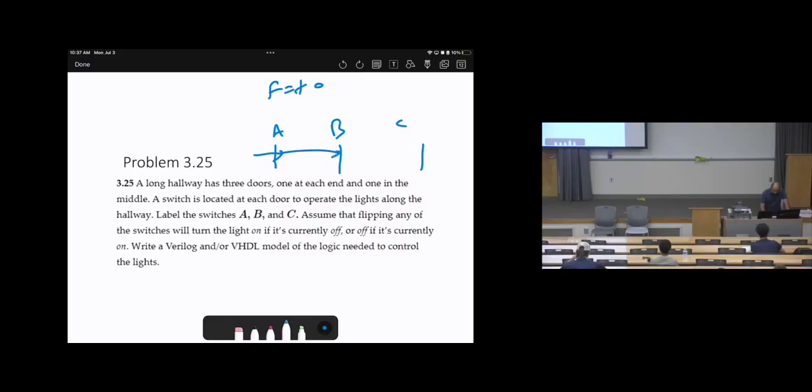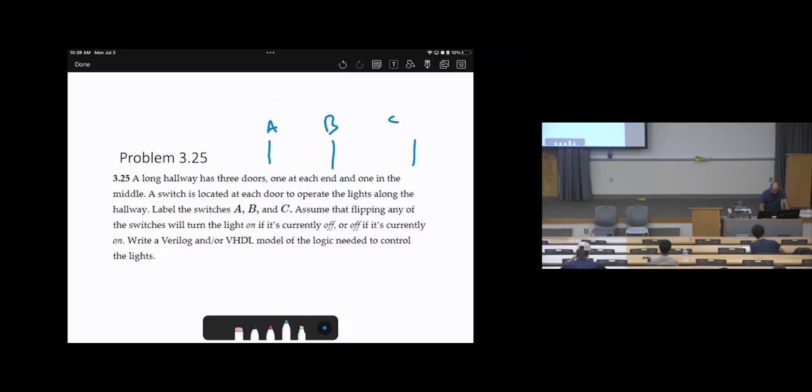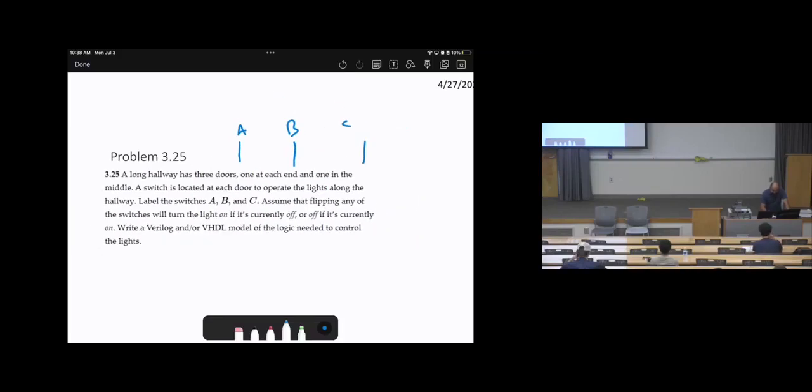We will realize that we can count the sensor detections. Sometimes someone can enter this door, and someone can enter this door. What will happen? This will switch twice, so it will make F 0. If 3 people enter, this will make it 1, 2, 3, which is on, off, on, so it will make it on.